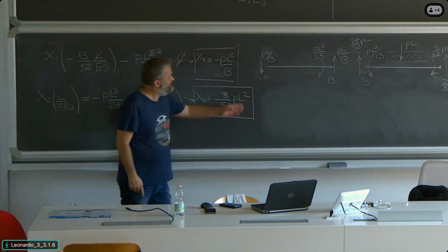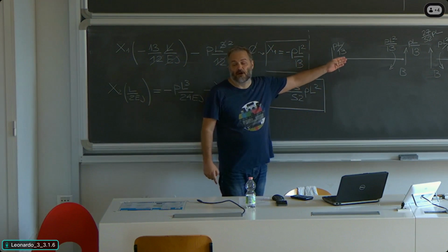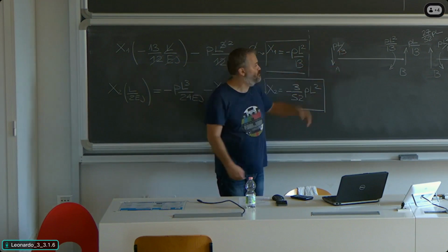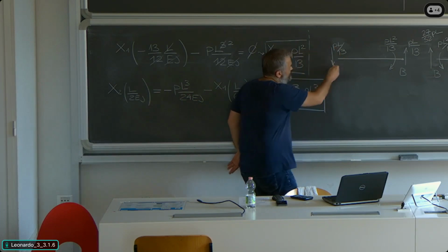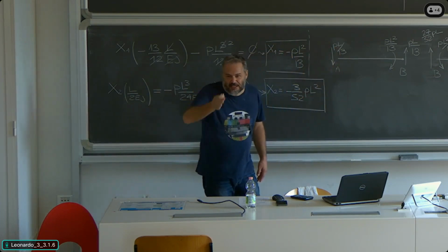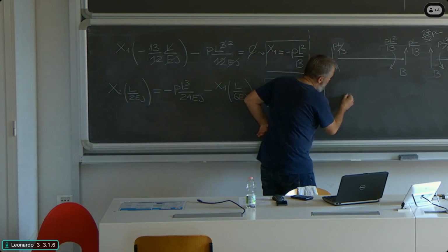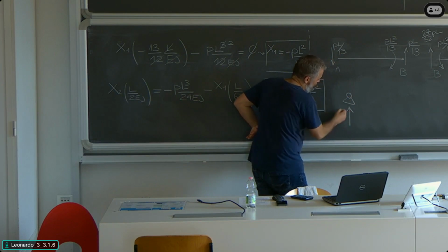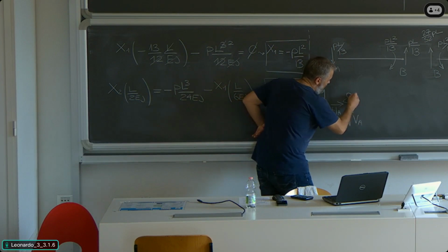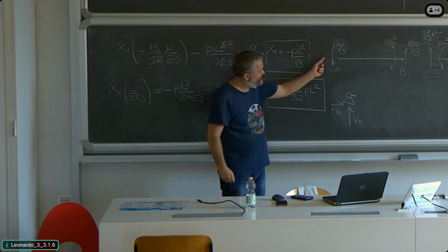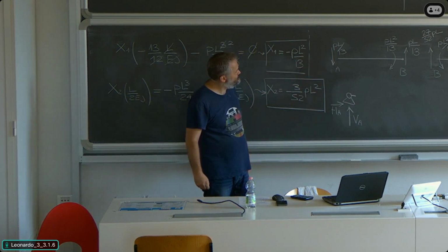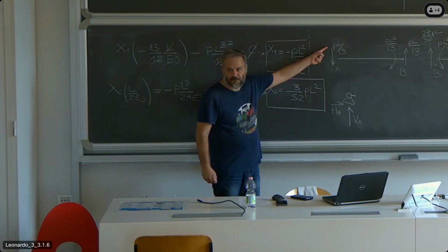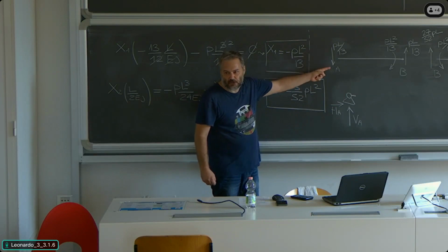We look at this point in the perspective of the beam. Now let's look at this point in the perspective of the support, which means here I plotted the beam just slightly after the support. Here I simply plot the support, okay? A hinge which has two reaction forces, which are HA and VA. Small portion of the beam, principle of action and reaction. The force here on the beam acts downwards.